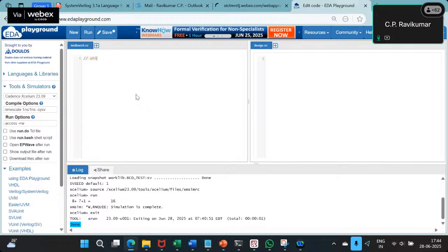Shift and add multiplier. So you may want to have an interface. You may have to have a class called shift and add multiplier. You may need a test module. You may need a way to generate random inputs or whatever to generate inputs. And you may need a way to test if the results are okay. So you need to think about all these things and then build a model.